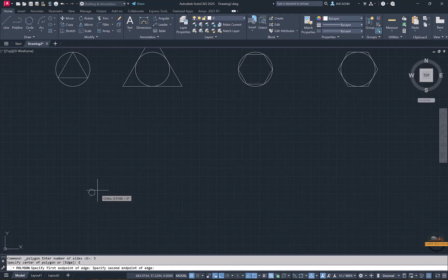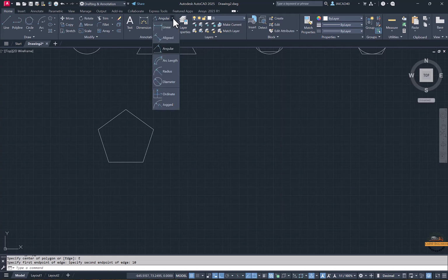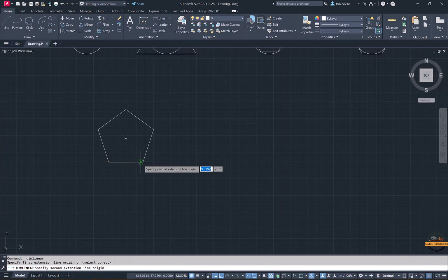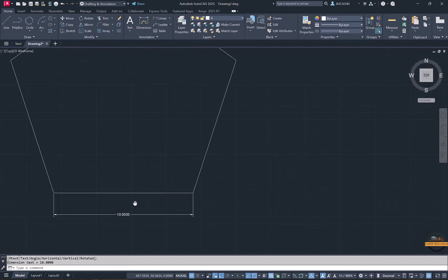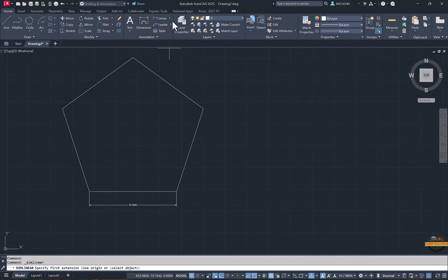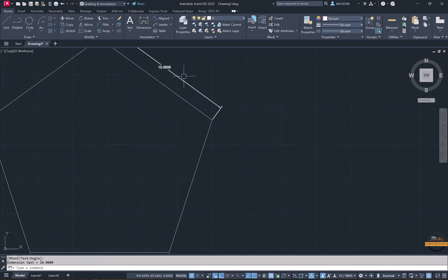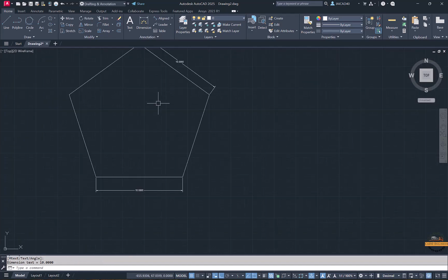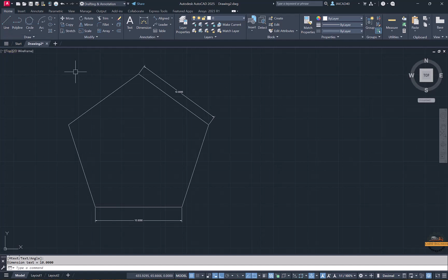We'll click edge, then click the first point on the screen. Now we can define the length of the side that we require. I said I require a side of like 10. So if you measure the sides of this polygon, each side will be 10. You can see that is 10. If you also check here with align dimension, you can see that it is exactly 10. Okay, so this is how we can measure and check the dimensions of a polygon.